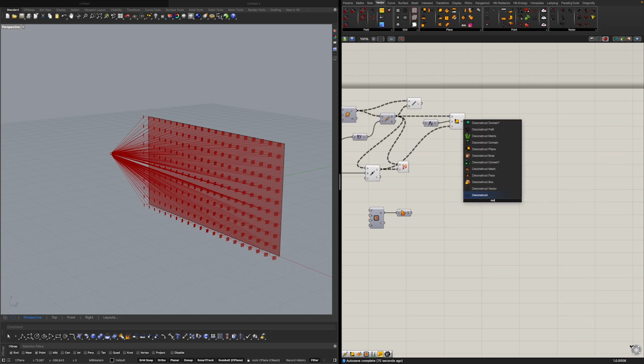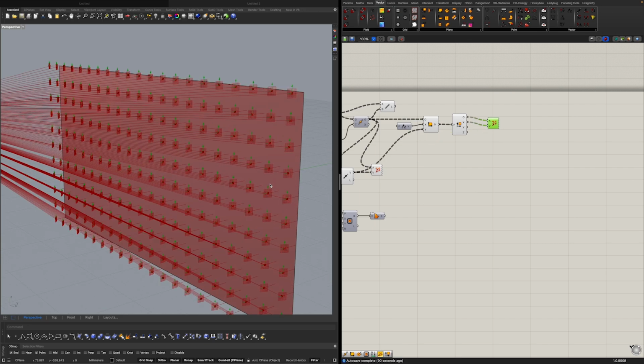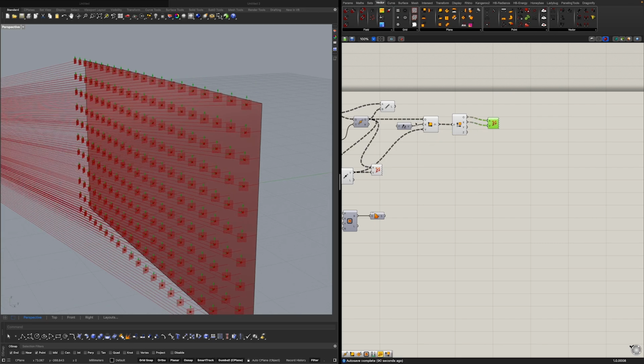I'm going to deconstruct a plane and see what is our new z-axis. And just do copy paste of this vector. So this will be the origin, and see we already used z-axis as x-axis, so that is our new x, and y will be towards the attractor point, and z will be our new vector.